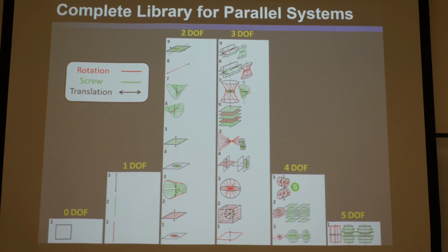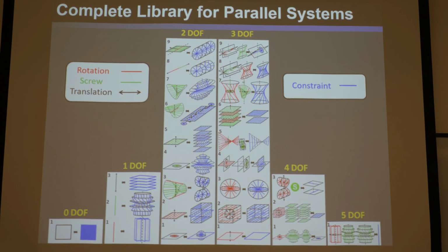Okay, so all these spaces uniquely map to complementary constraint spaces, which are really pure force wrench vectors. And the reason we just look at the pure force wrench vectors is because that's all that's really pertinent to parallel flexure systems. Parallel modules or parallel elements are just modeled by the blue lines that pass through their geometry, as you're familiar with wires and blades and those things. So we're really only interested in the blue space, but the motions we're interested in are all 3: rotations, screws, and translations.